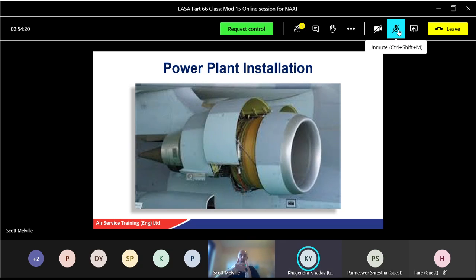Okay, just by purely nut and bolt action, the bolt would spin if it seized, because the turbine would keep moving. Move the little bell crank. The bell crank was a mechanical lever, so the nut would move the lever. The lever would be attached to a cable all the way to the front of the engine and switch over. That was a mechanical version.